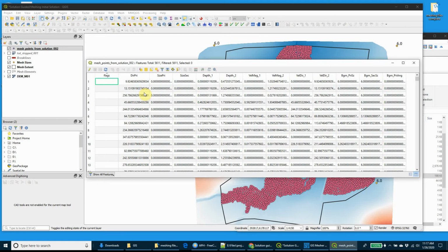So it's set up to favor the first one that we read in. We did the low flow scenario. If it was wet in that scenario, then it's going to be oriented in that direction. If it wasn't, but was wet in the high flow scenario, which all of the points that are kept were, it orients them based on that high flow. So if we have little wiggles that are in the low flow but not in the high flow, they're going to get captured as the wiggles in our mesh. So our mesh will be able to be valid for low and high flow.